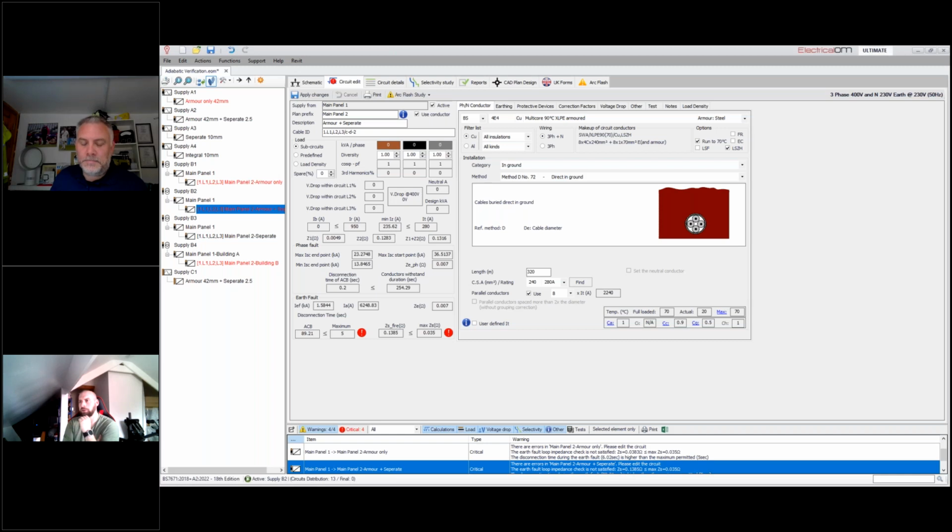I think we've got a question about, I'd imagine this is maybe during verification or maybe EICRs, is the answer to check and upgrade to the separate CPC to ensure compliance? The thing is, unless it's part of the design or you've got the design, you've got to be very careful about just going along and adding a separate CPC, because you could actually have a detrimental effect on that.